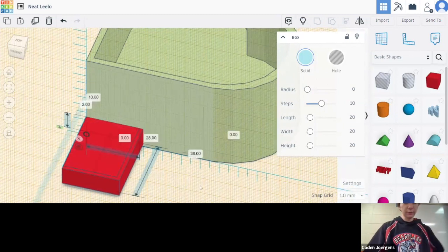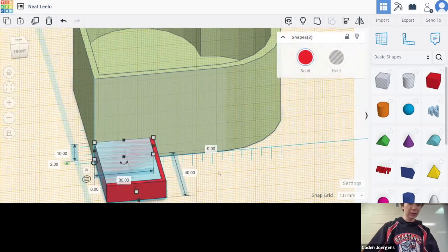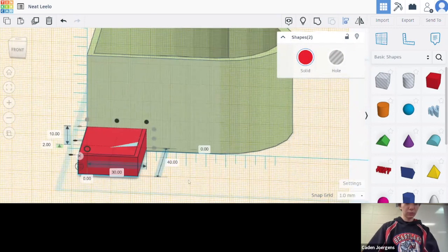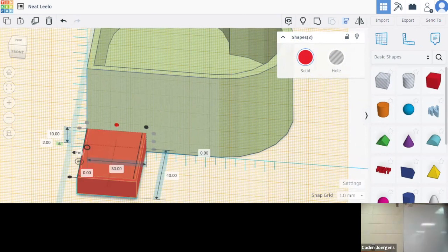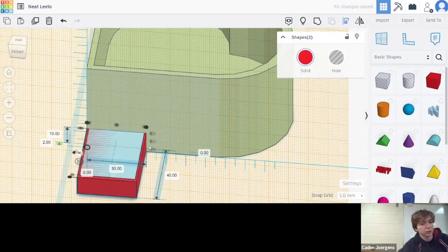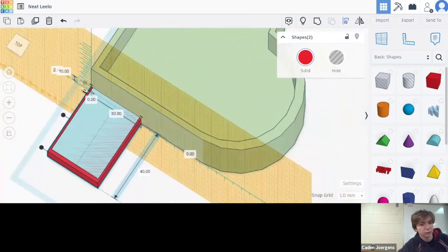But before we go any further with this, we are going to select all of it, and we are going to go back up here to align, because we're actually going to use it this time. These buttons will preview different places that you can align things to. The farthest corner is going to align it over to that side, so their edges will meet up. That's another form of constraint, having your edges meet up. So we are going to hit this middle one because we want them to be aligned down the middle. And then if we move around, we can see we have a few other constraints.